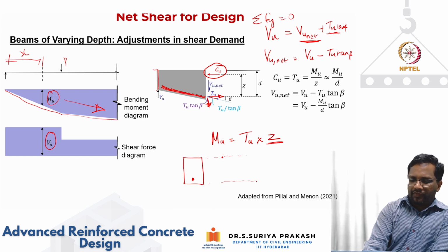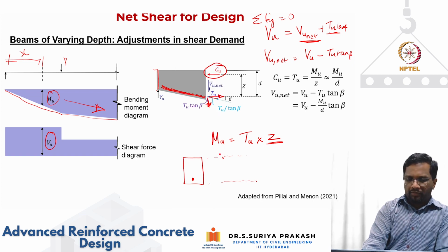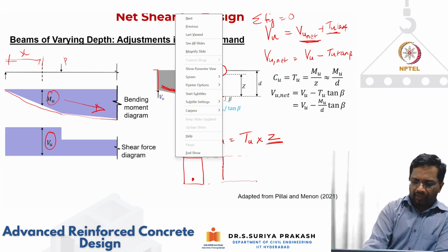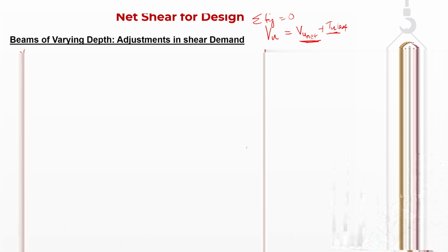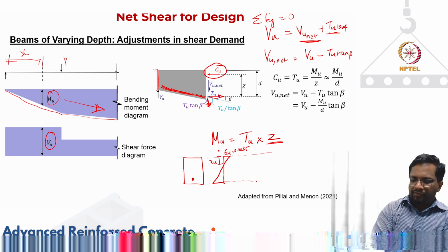What we are saying is, we know from your force diagram, let's say this is your strain distribution that I have. Let's say this is epsilon c equal to 0.003, that is what we did. So your neutral axis depth that is required to satisfy equilibrium will usually be very low at ultimate, right?